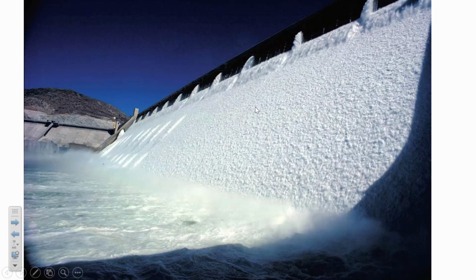When the water is going down the spillway, it's flowing at supercritical conditions because that's a very steep face, and the water gains a lot of velocity. Then when it gets to the bottom, it still has all of that kinetic energy tied up in the velocity head, and it goes through a hydraulic jump.